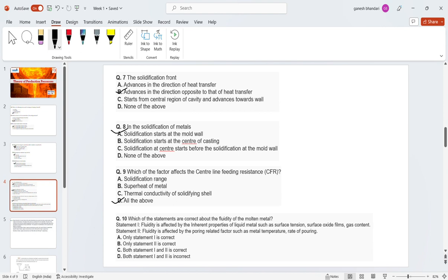Suppose on your surface tin oxide is present, and at the core majorly tin is present. The melting point of tin is around 250, 254, or something slightly higher. So the core will be in a molten state, but your surface won't be in a molten state. Since the outside is not molten, it won't allow your core to flow outside, because it is present in solid form.